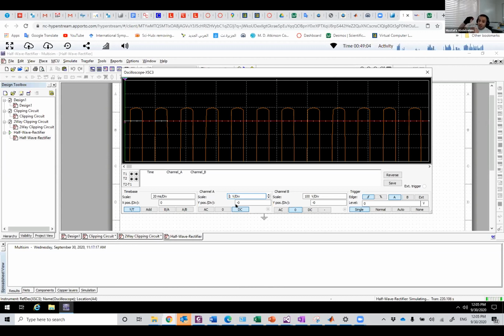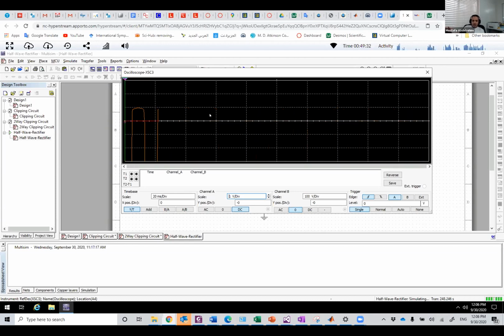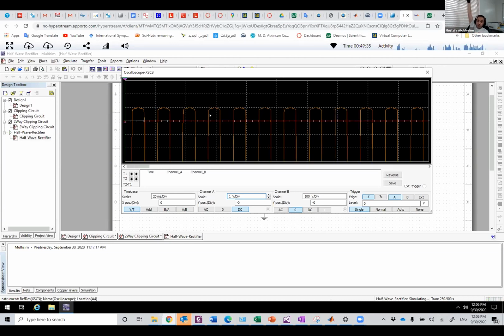But if you increase the input voltage too much, then it will exceed 0.8, no problem in that. So here, the diode, when it becomes on, stabilizes the voltage at approximately 1 volt. That's why the clipping voltage is 1 volt, which is still very close to 0.7. And both, compared to 155.5, are very small.